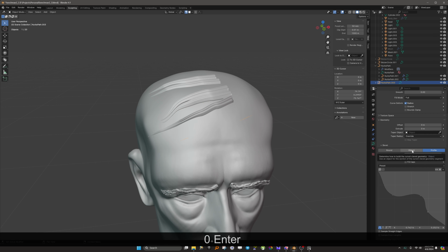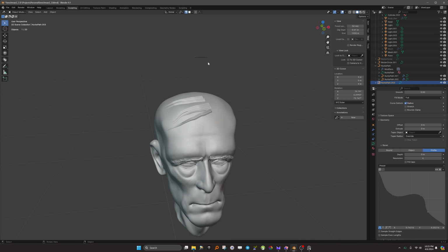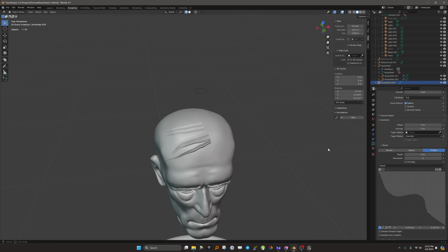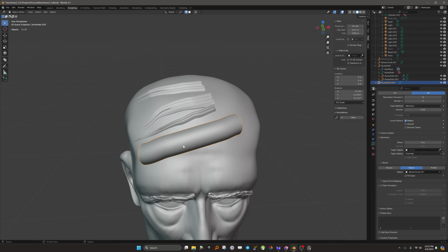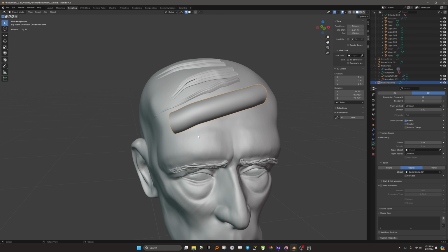What I want to do is to be able to use our little friend up here, this circle. I want to use an object, and so I just use the eyedropper. You can either use the eyedropper, or, and I have named things horribly, so when I click on this, you're just going to see Bezier circle and NURBS path, and I couldn't tell you which is which, so I'm not going to bother. I'm just going to click this and then click the object. All right, so now we have a big fat curve.